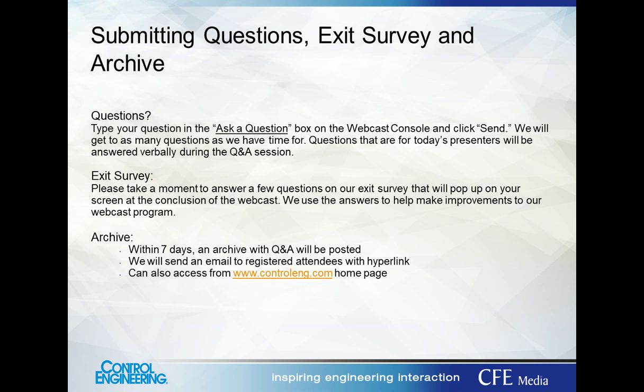But if you've been a control engineer as long as I have, you've seen a pattern, which is that a site may embark, maybe they're tired of tuning issues coming up all the time or modeling issues with MPC, and so they embark on a campaign to use some new tools and go out and retune everything. But when that's over, what happens is there's an increase in the fact that you've got to go back and actually detune or retune, or in the case of MPC, dial in some move limits or extend some control times.